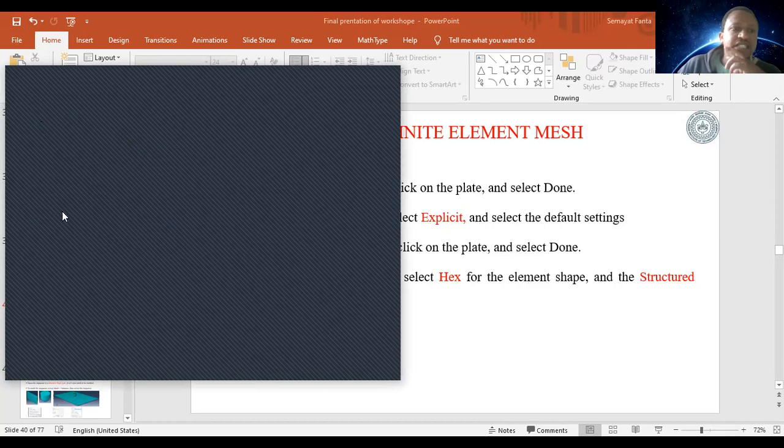For element deletion or degradation, we can take default or we can make element deletion. Once the element is damaged, it will be deleted. So element deletion is selected, so that we selected COH3D8. That means an 8-node 3-dimensional cohesive element is created now in explicit analysis. So that is hexa type linear mesh type.